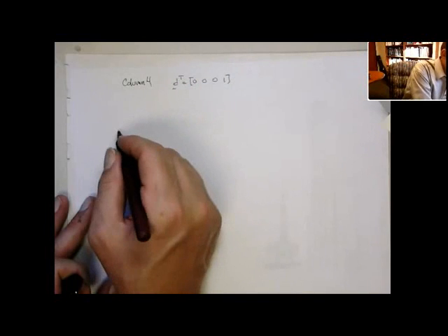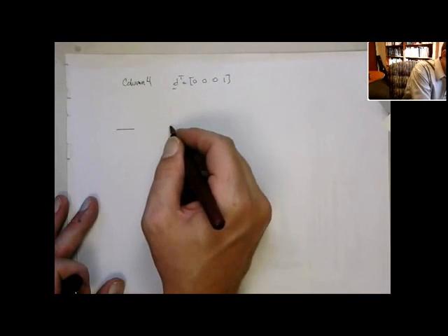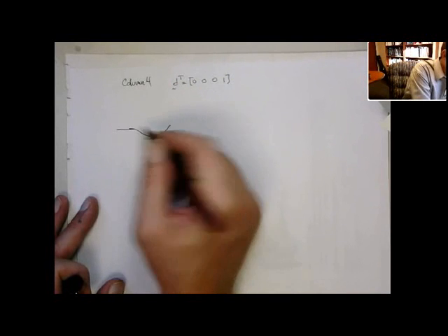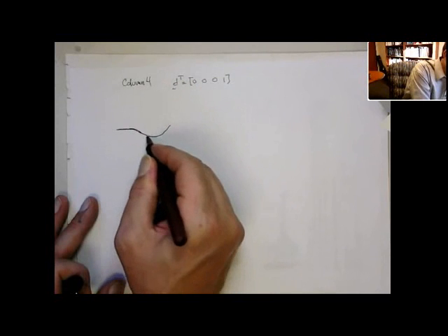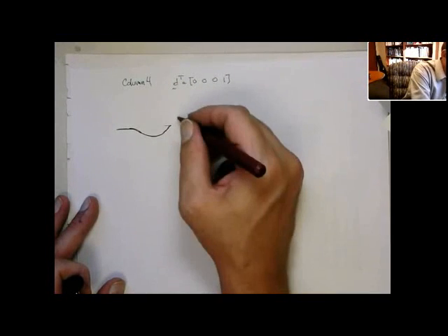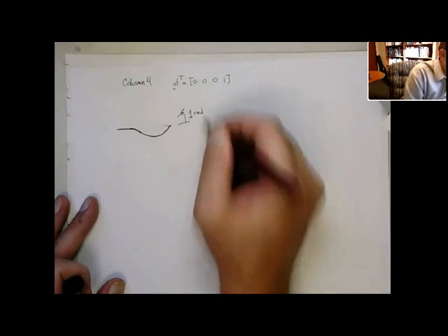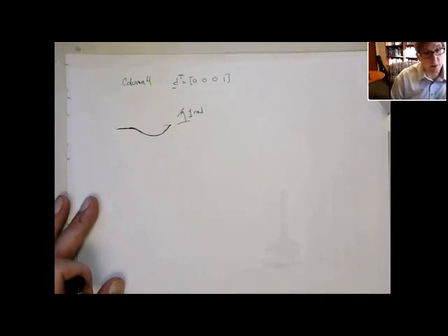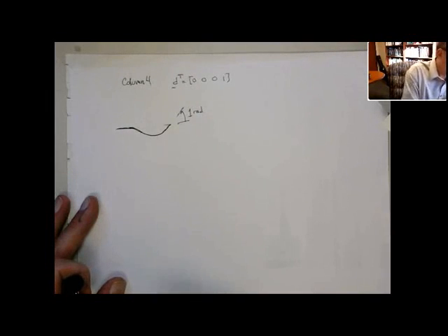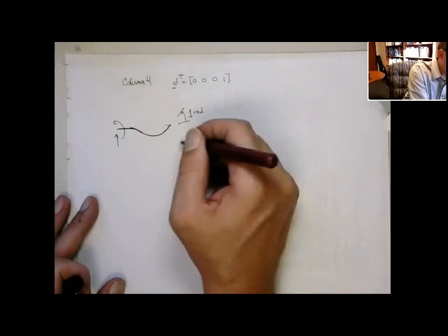So in that picture, we're fully fixed on one side, and then on the right side, we have this positive rotation. So it has to be something like this. And the deflection is 0. This has a rotation of 1 radian. Remember, the angles are always in radians. Okay, and again, when I plug this in, we can get the forces and the moments.